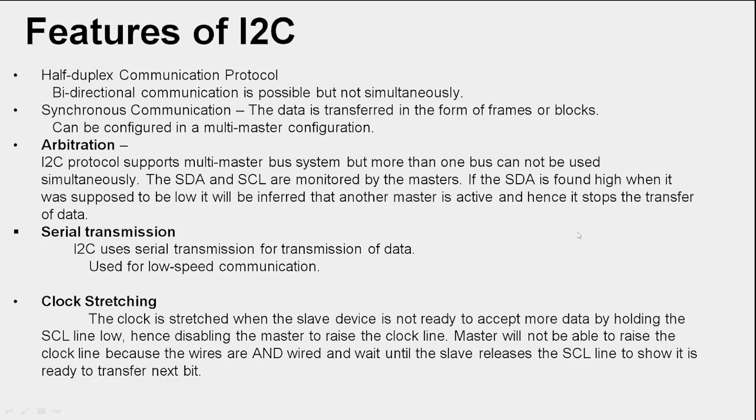Then there is clock stretching. Whenever the device is not ready to accept more data, it holds the SCL line low, hence preventing the master from raising the clock line. That is called clock stretching.